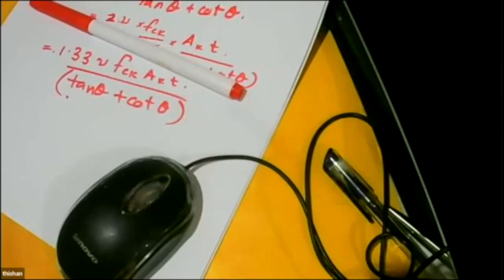Because you have to adjust the beam. But you have a number of walls; some are on the center line, some are not. Then you need a rigid arm. But if it is a very long wall, don't put it as an eccentric wall. Always negotiate with the architect and make it a wall coinciding with the center line.